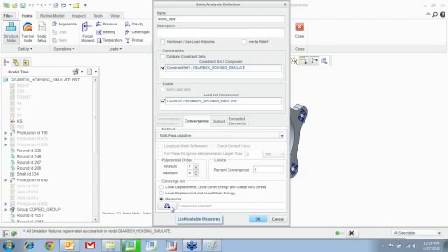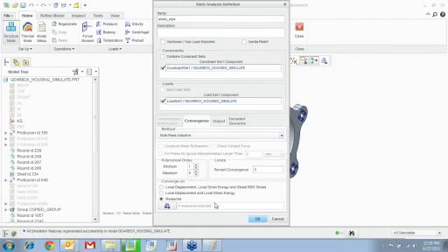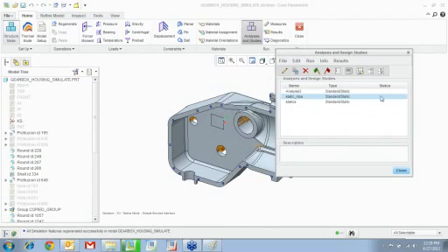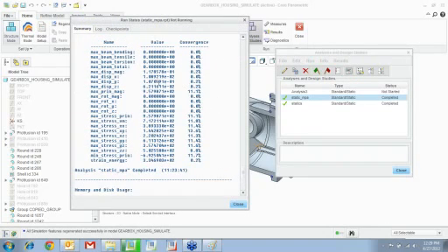What gets compared is also controlled by the user by selecting measures. See, I've selected displacement, von Mises stress. I can pick a bunch of them by pressing control and say, okay, I have 4 measures selected. All right. Now, if we look at the results for this, you can see our area of concern was displacement magnitude.